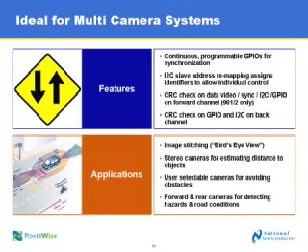Okay. Also, there's stereo cameras where they put two cameras in a direction, either looking backwards or forwards. And really, the idea with the stereo camera is now you can see distances. You could judge the distance, just like we do with our eyes. And also, for machine vision systems that are looking for dangerous situations, it's actually fairly easy to see something going across, because then you could just look at the change in the pixels, and you can calculate how fast, say, a vehicle's moving or a bike or something.